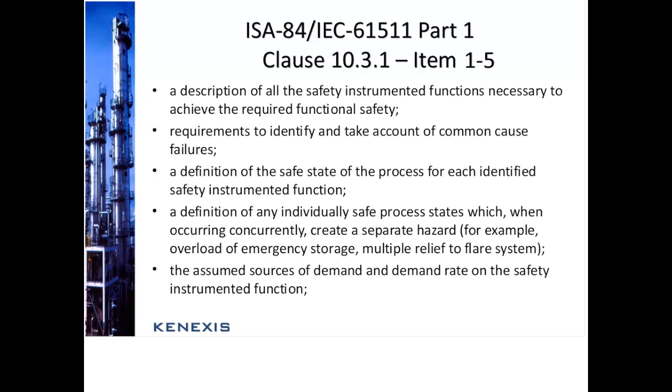These are the types of things that need to be looked at and evaluated, particularly if one safety instrumented function, such as the downstream vessel on a liquid leg out of another vessel, would shut down. It might present a high-level hazard to the upstream vessel.